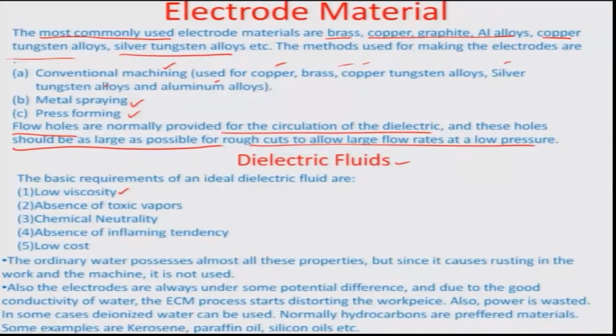low viscosity, there should not be any surface forces of drag which would come out, which may change the orientation of the tools, particularly in thin tools. There should be absence of toxic vapors. By and large, the dielectric fluid should be chosen in a manner so that it is chemically neutral, not able to react to any other part of the supports or the tool holders, etc. There should be generally a low or almost negligible inflaming tendency.